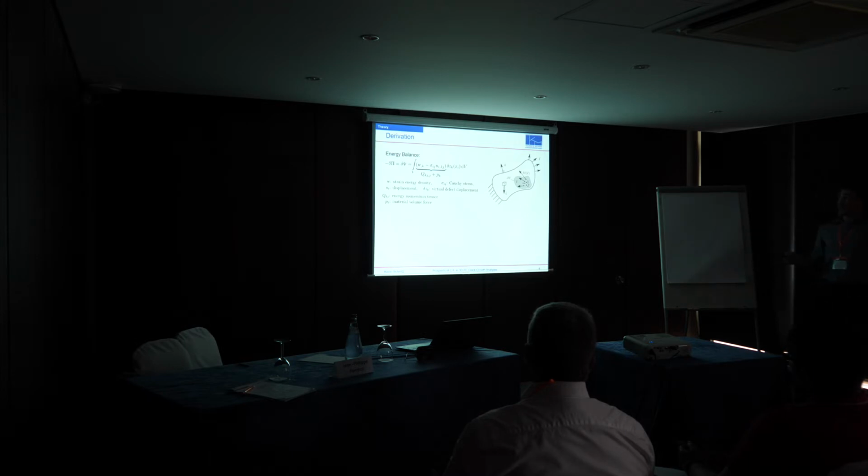We write down the energy balance due to a movement of the defects, and then can obtain a weak form of the potential variation due to a defect displacement, where the derivative that we see here in the energy momentum tensor is transferred to our virtual defect displacement function, which acts in this formulation as a kind of test function.